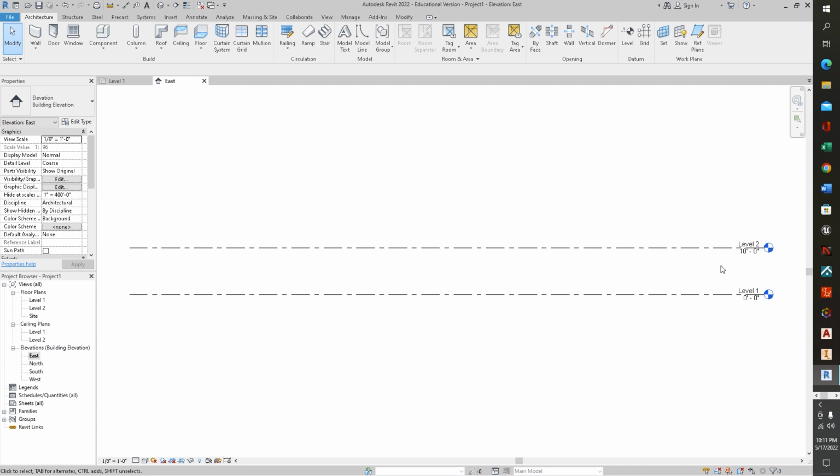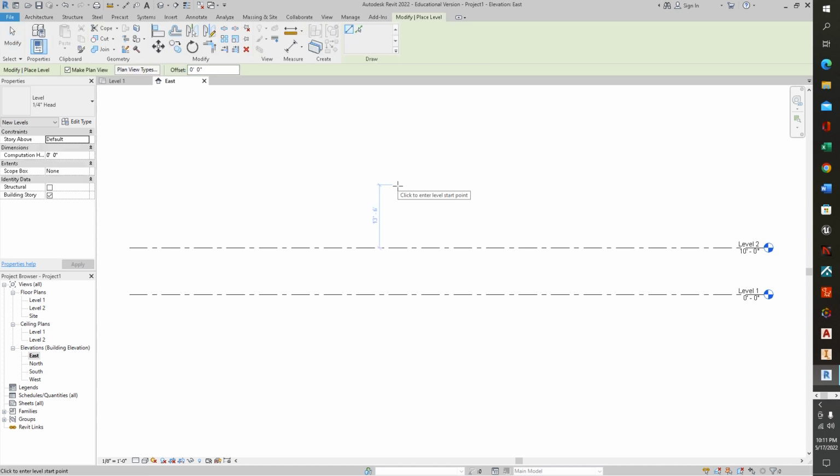If you're designing a house, you obviously know how much space you're going to want between levels. But we'll start with 10 feet. It's a pretty generous amount of space for a residential building. Your framing isn't really going to be that crazy on it. We'll keep with 10 feet. And what we're going to want to do is add in some more levels. This is your ground floor, one floor up, so your level 2 starts from there, and then we can add in different levels above and below it. To do that, we type LL on our keyboard.